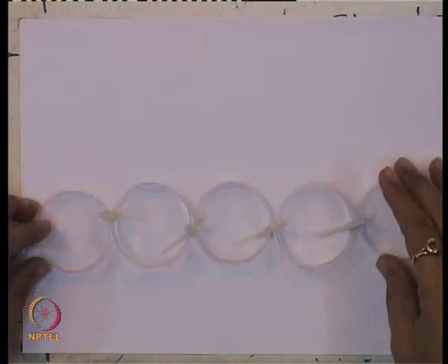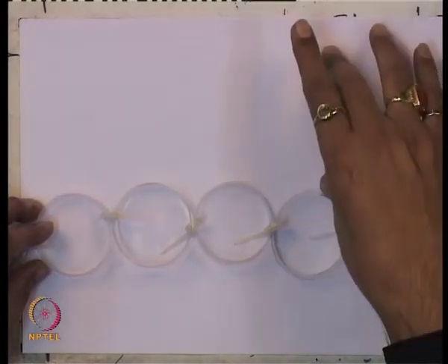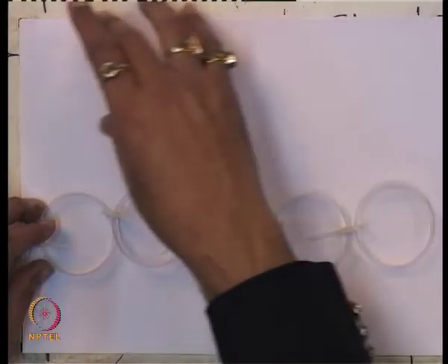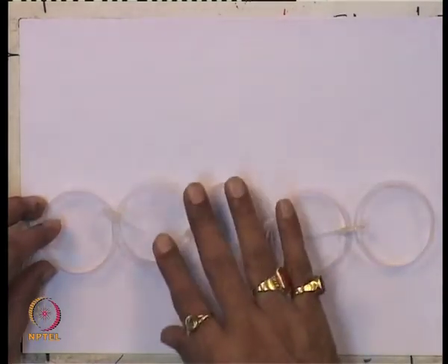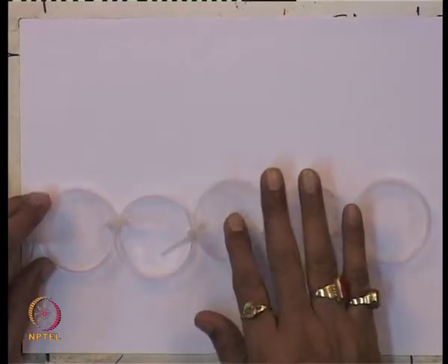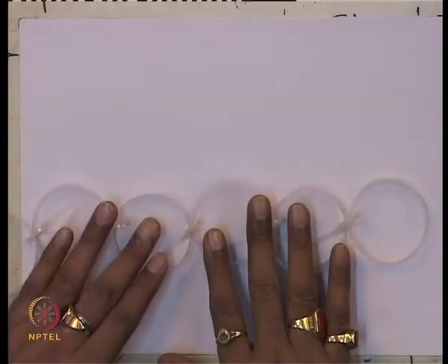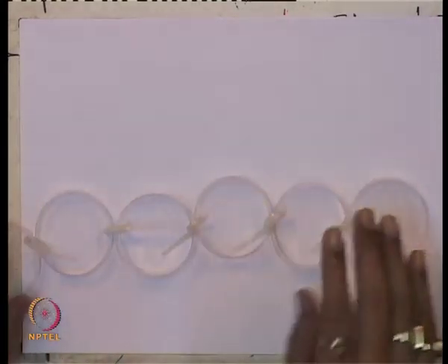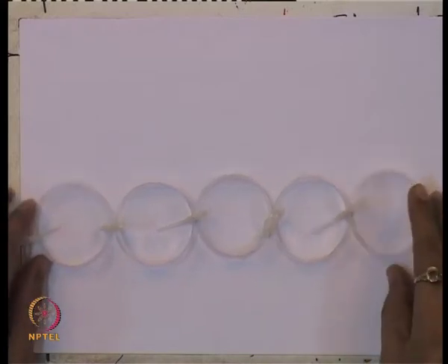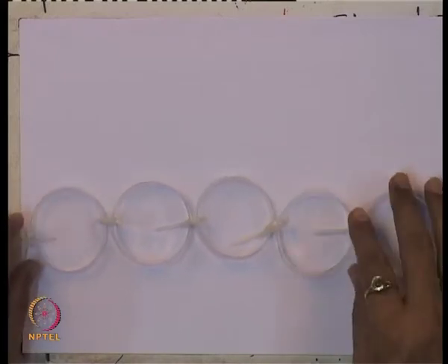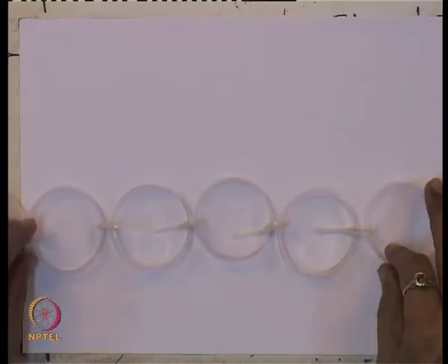Also, you can use the geocell in strip form. You can give the spacing and then put another strip of geocell, and this geocell can also be filled up with fill and compacted. This kind of system is adopted in this experimental program.